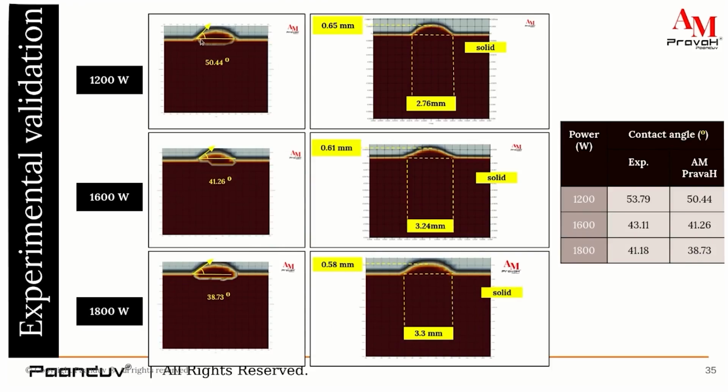Now the interesting part here is at the end, at the corners, you see smaller grain sizes, but at the middle, you see much larger grain sizes. Why is this happening? We have provided a particular hatch spacing to the system, because of which the remelting is happening at the center part.